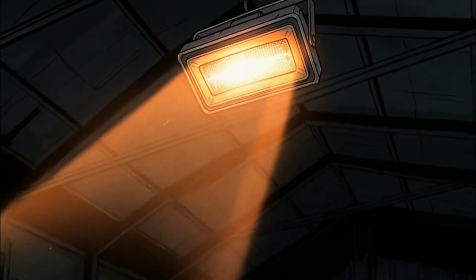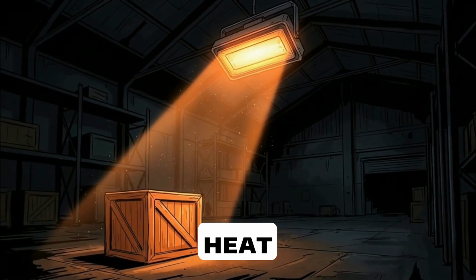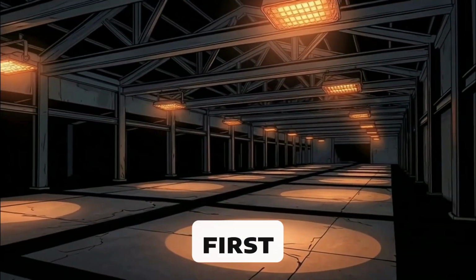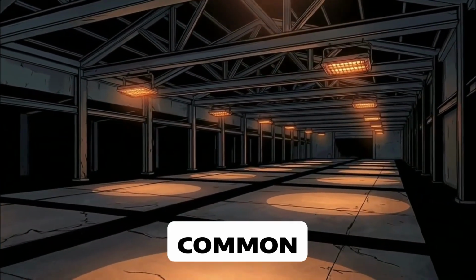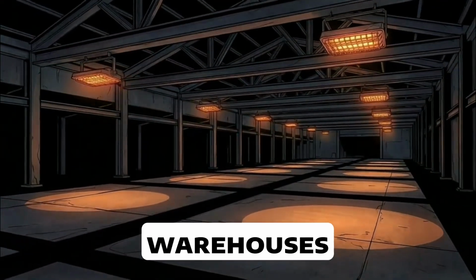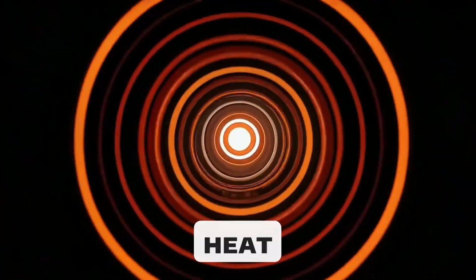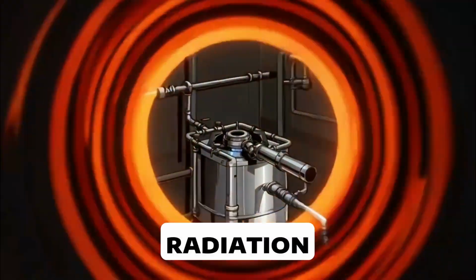Now, infrared heaters. Infrared heaters heat people and objects directly instead of heating all the air first. That is why they are common in garages, warehouses, loading docks, and large open spaces. Their primary heat transfer method is radiation.